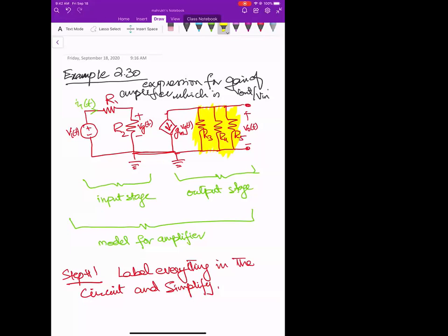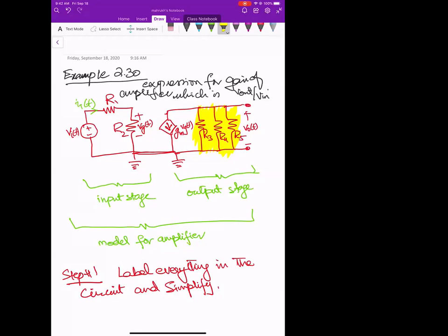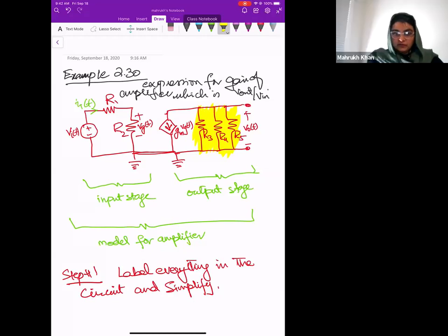Isn't the voltage dispersed the same throughout all the resistors? So if you make an equivalent, it'll still be the same? Yes, exactly. Yes, because you do not have any component between these 2 points or nodes, or these 3. So they all have the same voltage. So they all have V naught of t, right? So what you should say is, you will not change V naught of t if you simplify this, okay?